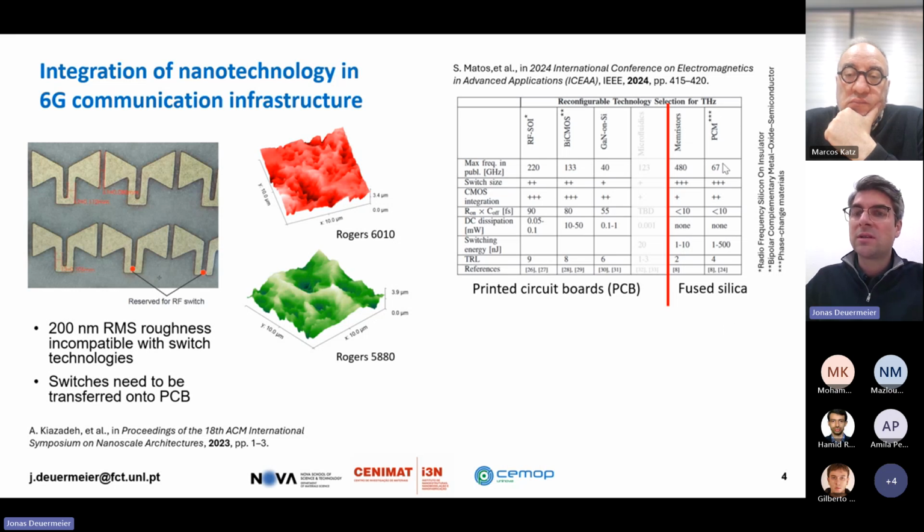Another thing which I'm going to explain a bit further is miniaturization. Memristors in particular, and the ones we're working on, can be made very small, and this is a big advantage for boosting the operation frequency, because as it gets smaller, we're basically decreasing the off capacitance, and the on resistance can still be high because of the mechanism of switching, which I'm going to show in a bit.